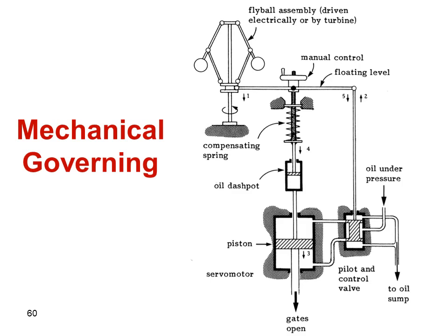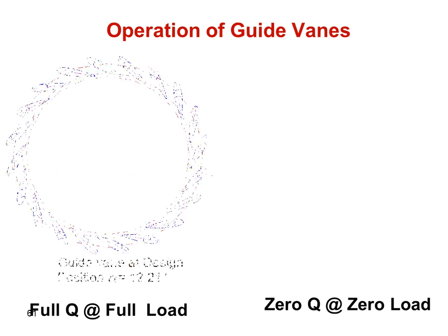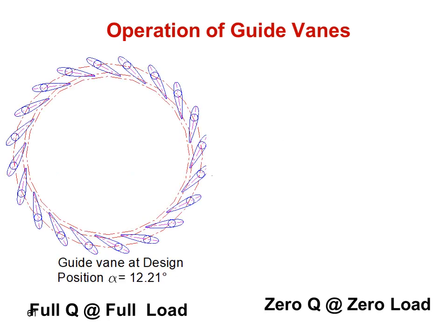Here, this is a governing system. We have a mechanical governor and hydraulic circuit that can be used during the load drop, in order to reduce the flow rate to be proportional to the reduced load, in order to keep the turbine speed constant. During its opening, as we see here, the flow passes through, water flows in the spacing between the guide vanes, and goes to the runner inside this circle.